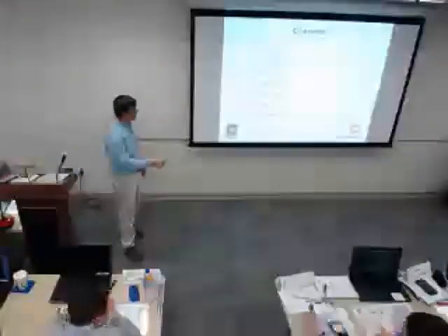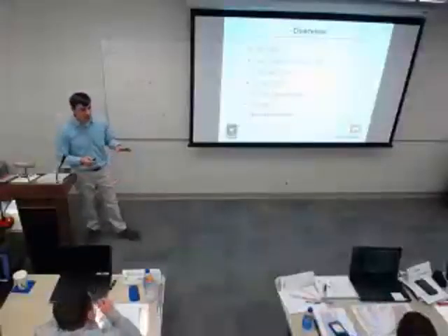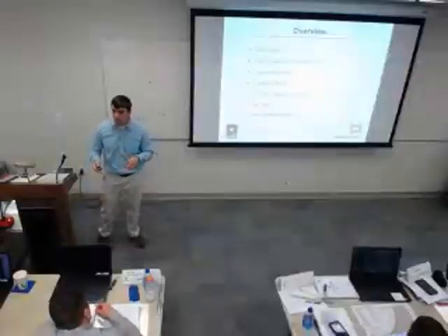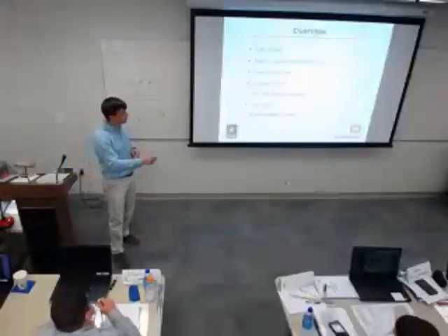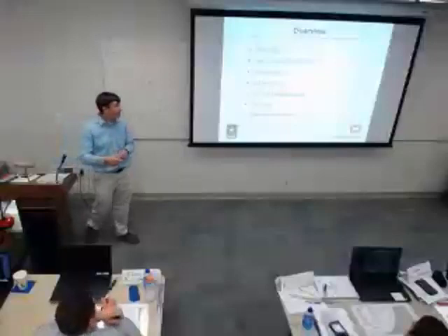The operating point is the intersection of the system curve and the fan curve. So we've got a fan curve. The fan is going to operate on its fan curve. It doesn't have a choice. It's dumb. It just spins at whatever speed it's spinning, and then the physical characteristics of our system are going to dictate what airflow that fan actually puts out.